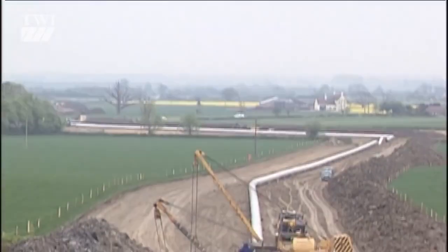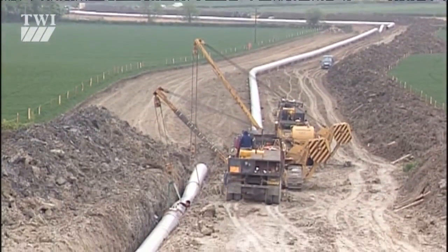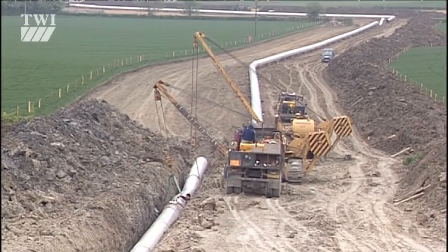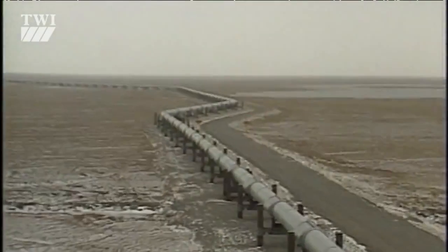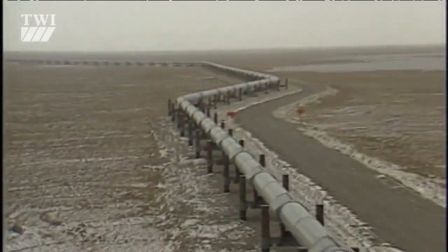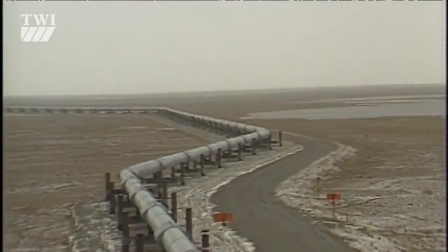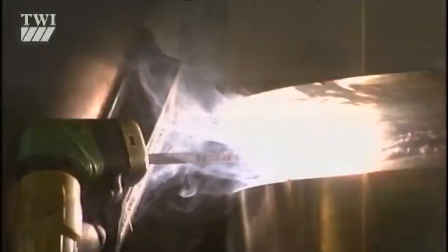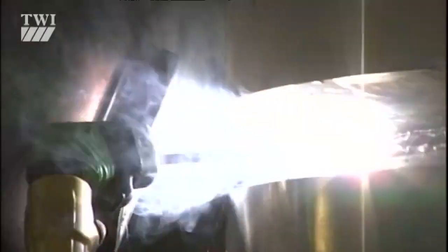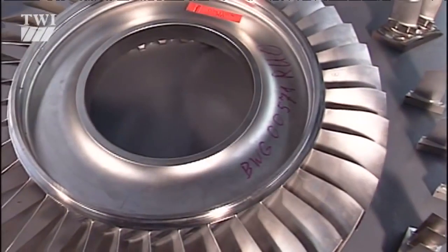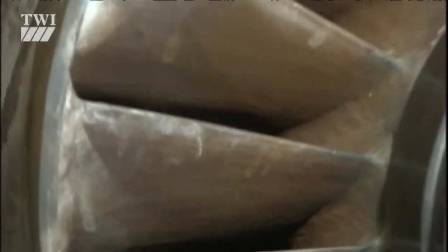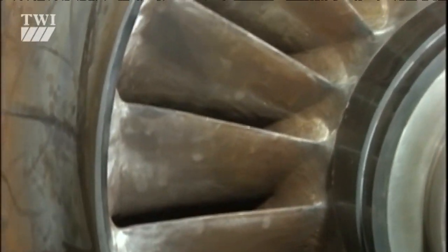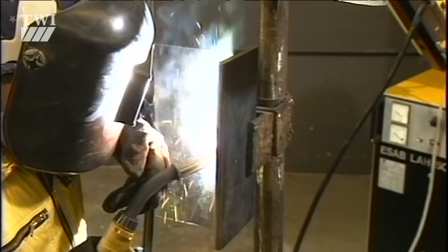A specific application of phased arrays lies in pipe girth weld inspection, particularly in installation of long pipelines, where it replaces conventional systems with many probes. This technique is also used for the rapid inspection of thick-section pressure vessel welds, turbine discs, shafts and blade roots, fillet welds, and welds in coarse-grained materials.